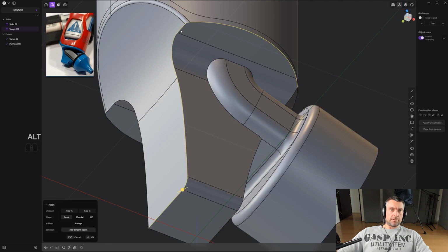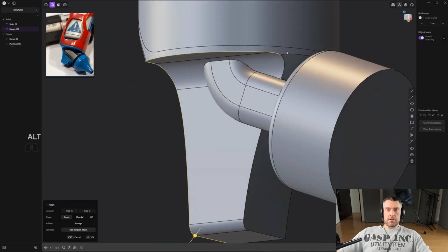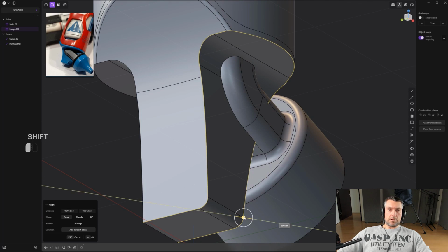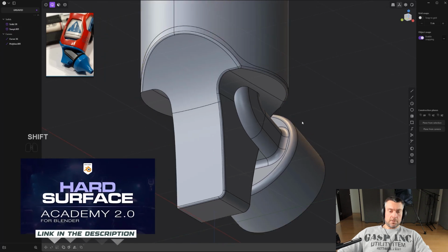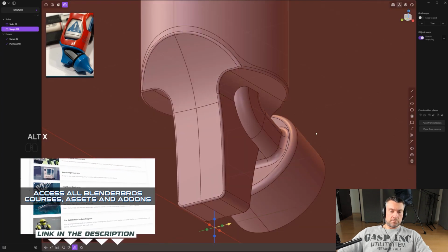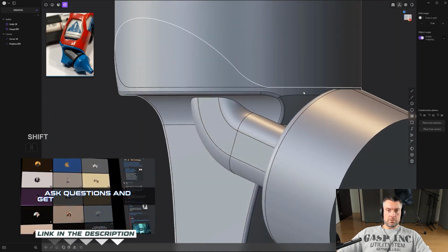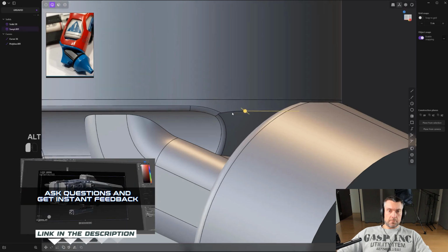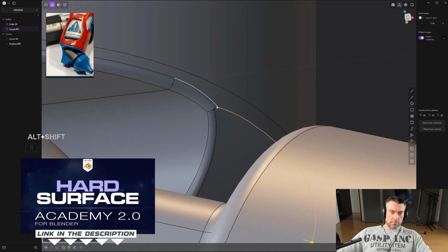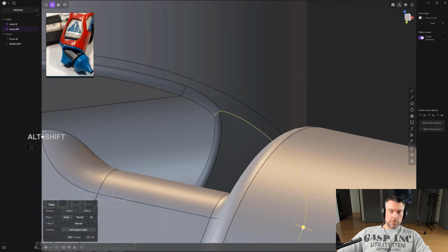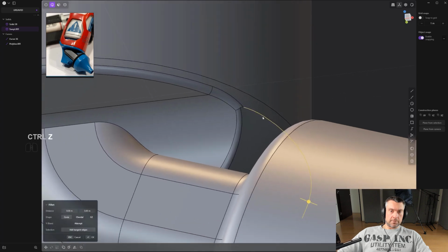Then if I alt click this, you will see that we're going to have a flawless bevel all around, I think, right? Okay, and then we can mirror this. So tiny bevel here. This will be fine. And then we can mirror it to the other side. So Q. Now when you're creating these macro bevels, make sure that you're not doing anything crazy in the more detailed mesh, because it will not work. Right? See, like here, good luck doing that, right?